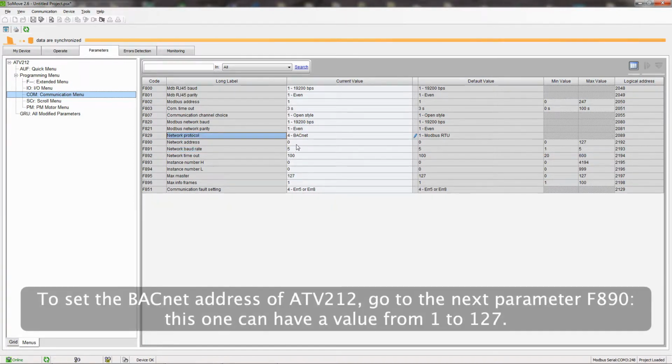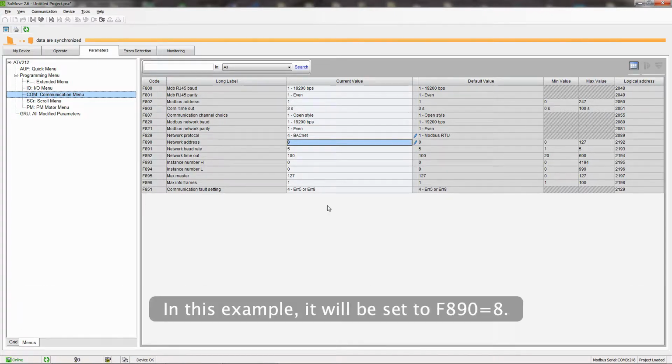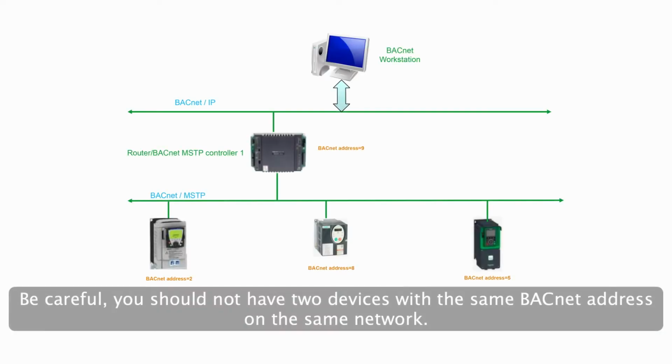To set the BacNet address of ATV212, go to the next parameter F890. This one can have a value from 1 to 127. In this example, it will be set to F890 equals 8. Be careful, you should not have two devices with the same BacNet address on the same network.